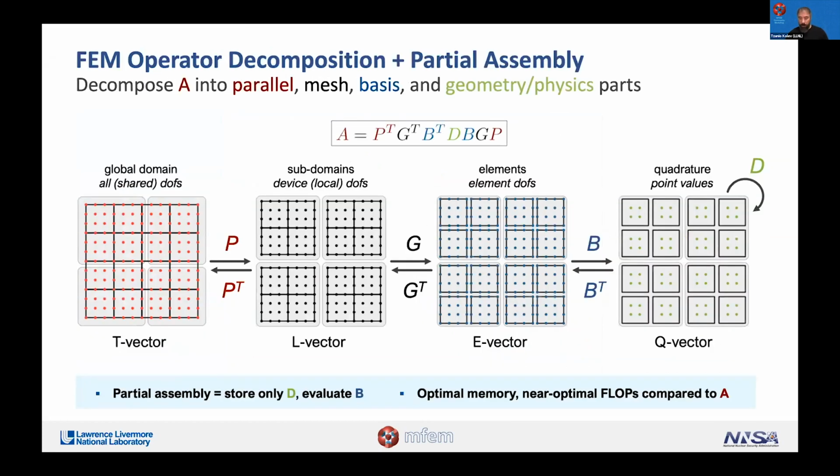Okay, the third thing I wanted to highlight, and that's the last one, is the GPU capability. I mentioned the seed project that motivated this. And the foundation for a lot of this work is the operator decomposition and the partial assembly of finite element operators. And the idea there is that any finite element operator can be split in this form.